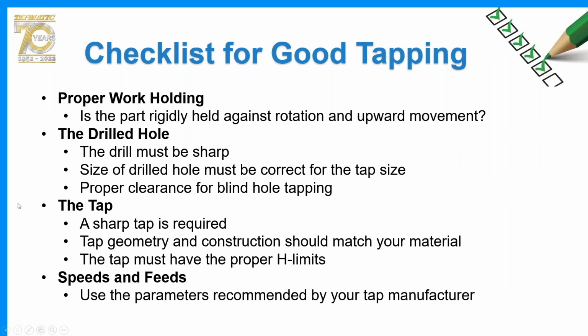And this is a checklist for good tapping. This could apply to titanium, but also any tapping. First, before you even begin the tapping process, you want to make sure that your part is rigidly held against any rotation and upward movement.